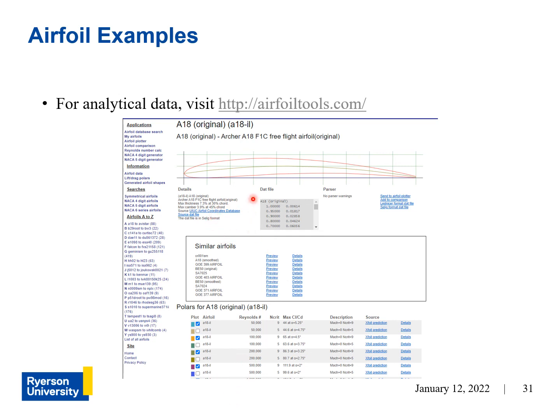And also you'll be able to find the DAT file, or the coordinates file, for the airfoil that you want to use. So if you're planning to CAD your airfoil, it'd be useful to have this DAT file because it contains the coordinates of each important point on your airfoil, and then you can use that to CAD your airfoil.